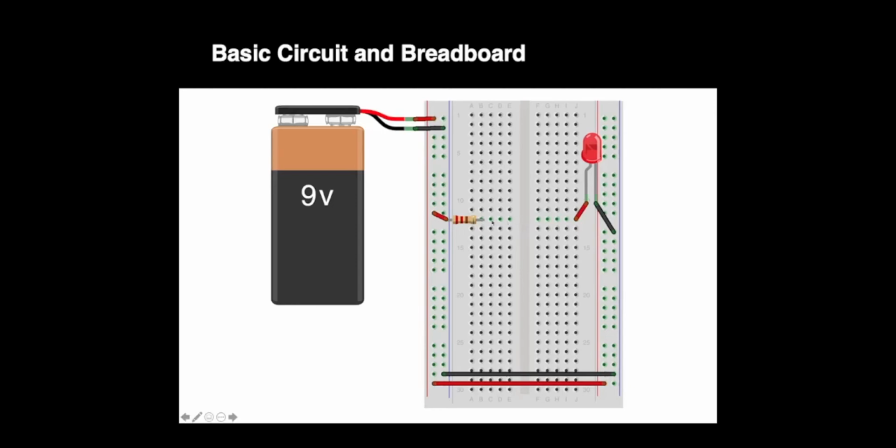Yeah, so this isn't connected to that. Because of that, this is just kind of empty here and broken. So the circuit isn't complete. You'd have to add a wire in between here and here, and that would complete the circuit. Because these columns and rows and these columns and rows are separated by this middle section, you have to connect it there to complete the circuit.